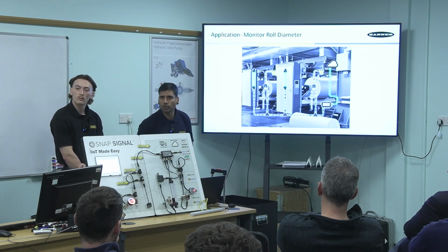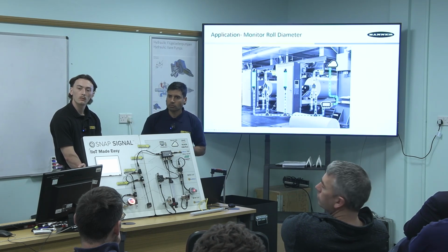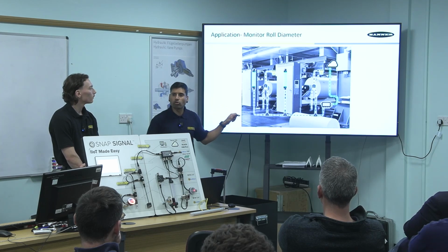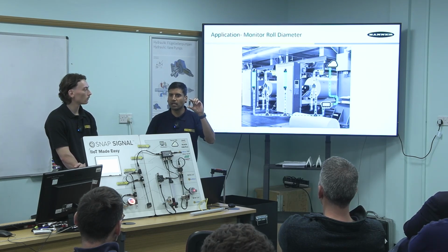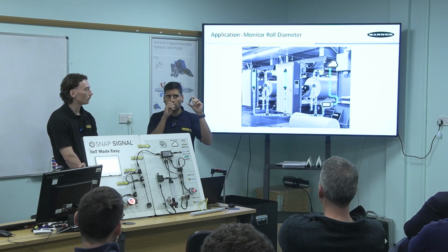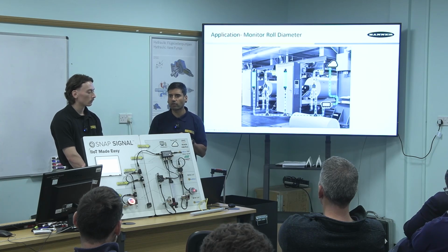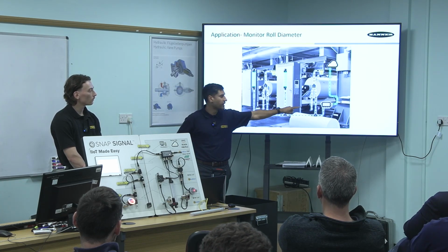Where's the calculation done? Yeah. That's converting the roll size, for instance, to a light? Yeah. So you scale it in the controller. So on these, this is an analog. So if it was a 4 to 20 milliamp analog converter, it's already in there scaled as a digital value, 4,000 to 20,000. So you then do the maths and the logic within this controller.